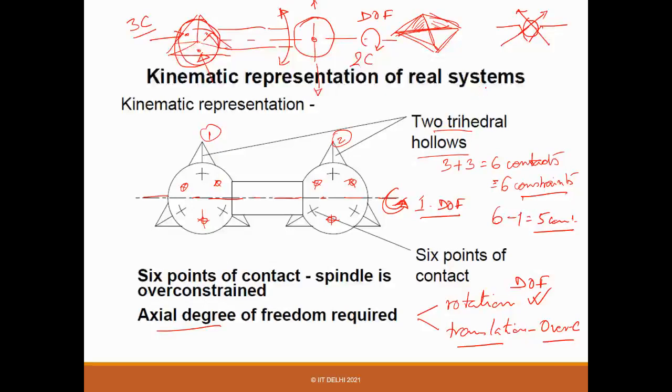So what will be the direction of the V? If you look carefully, one is definitely sitting on the base frame. So of course the V can lie on the surface of the table. But what you want is, you don't want to have this motion. So it means any V. So if you have a V along this line, this will not work, because then it can slide along this line, and it poses a constraint.